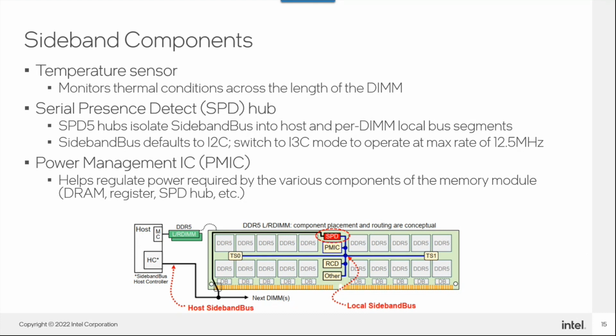Okay. Another question that we got before the session. Should I start thinking about upgrading my design to use DDR5? So what are the situations where people should start thinking about this? So from DDR4 to DDR5, if you are trying to use the same board and same pinouts, it's not going to work, first of all, because the footprints are different for DDR4 and DDR5. But if your application needs more bandwidth as well as power saving, then moving to DDR5 is a better choice. But again, the cost is also associated with it. DDR5 DIMMs or discrete components are a little bit expensive compared to DDR4. So there is a performance and power versus cost tradeoff.